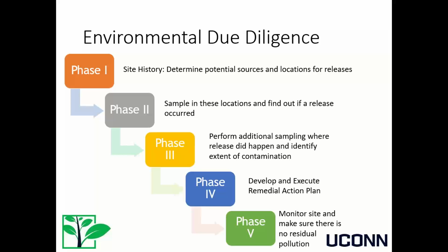Once we move to phase 2, the second phase of the environmental due diligence, we actually do environmental sampling in the locations where we suspect contamination, and find out whether a release has occurred or not. So that is a phase 2 site investigation.